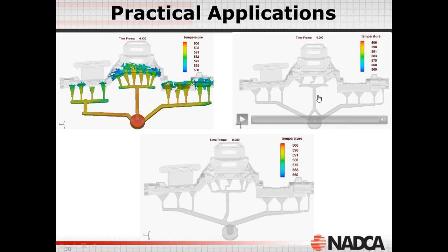as we see here. We change the center branch to have this Y, to have a delay going to the center branch, and also have a little stagger into the feet of the center gate. And we can see that we can have a more balanced filling. Material fills the middle as well as the two sides, so we actually got it very right.